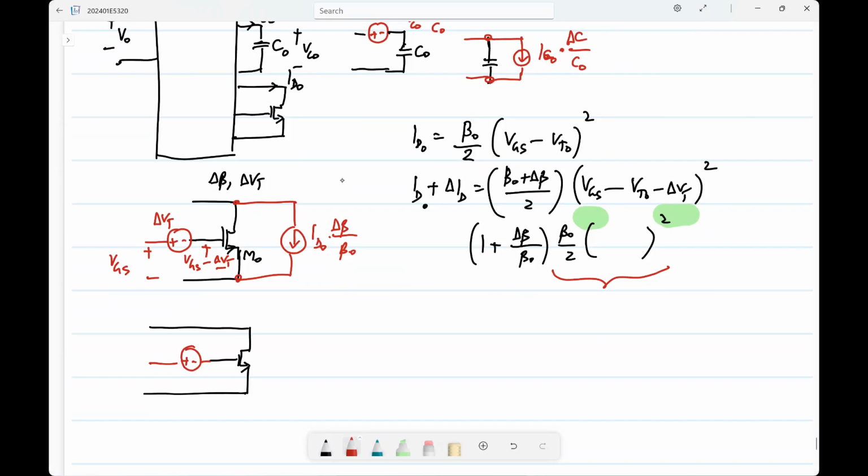Yeah. So basically, to get this additional incremental current, the incremental gate source voltage must be this divided by GM. Okay. So VGS has to increase by so much. Now the way this voltage source is defined, VGS is decreasing by that much. So this should be delta VT minus ID naught by GM times delta beta by beta naught. Okay. Is this okay?